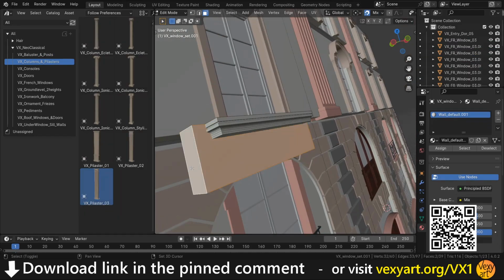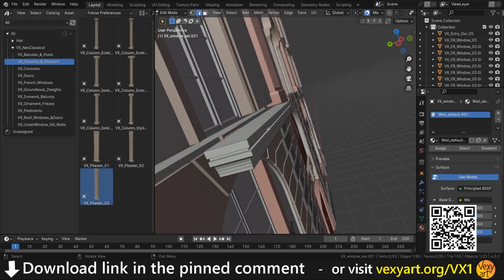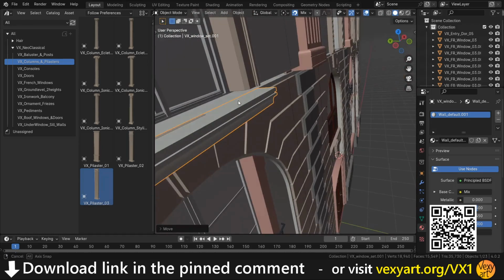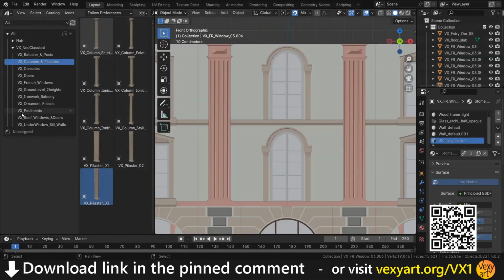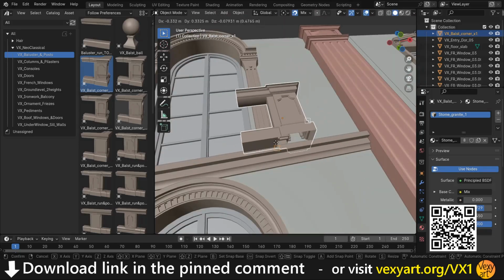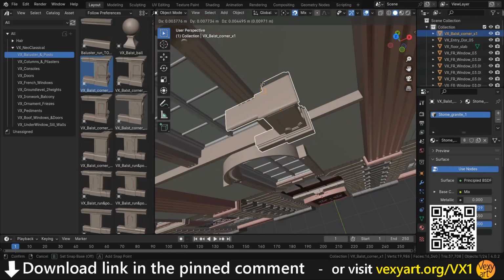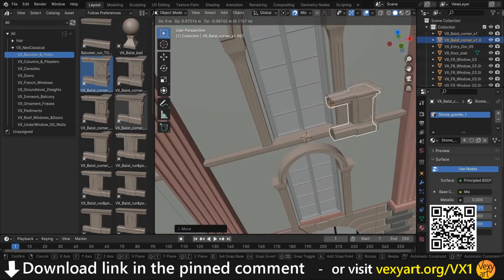Add small balcony extrusions to the windows to form the characteristic French balconies. Duplicate and place them below the rest of the windows. Next, we will add a balcony to the final central window. For that, choose a baluster style you like, add the balcony run and rail, and add the posts at the two ends of the balcony.